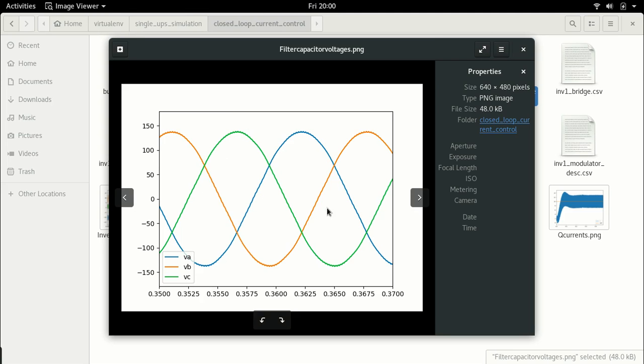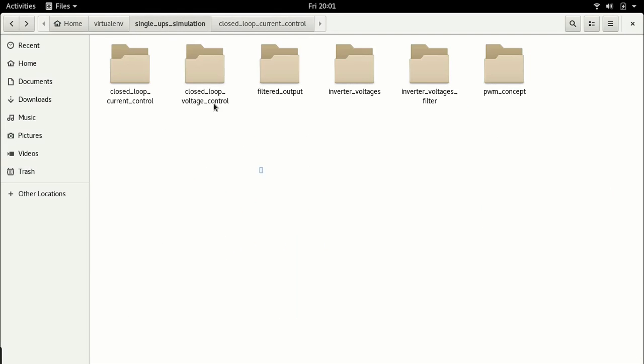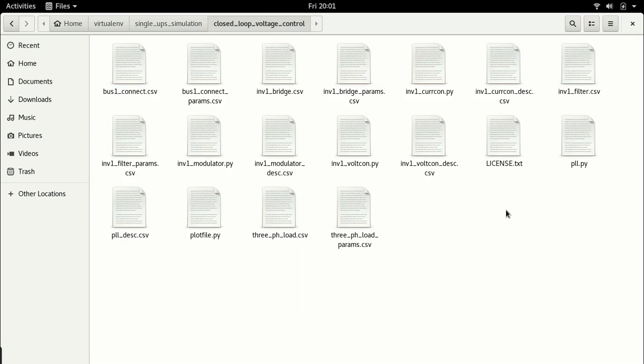I have balanced sinusoids. I have a three-phase balanced sinusoidal output voltage. So that's good. But it's not regulated to a magnitude yet. So this is still not good enough to apply to any particular load, particularly a load that's sensitive. So for that, what we have to do is we now go to the next stage, and that is we go over to closed loop control.